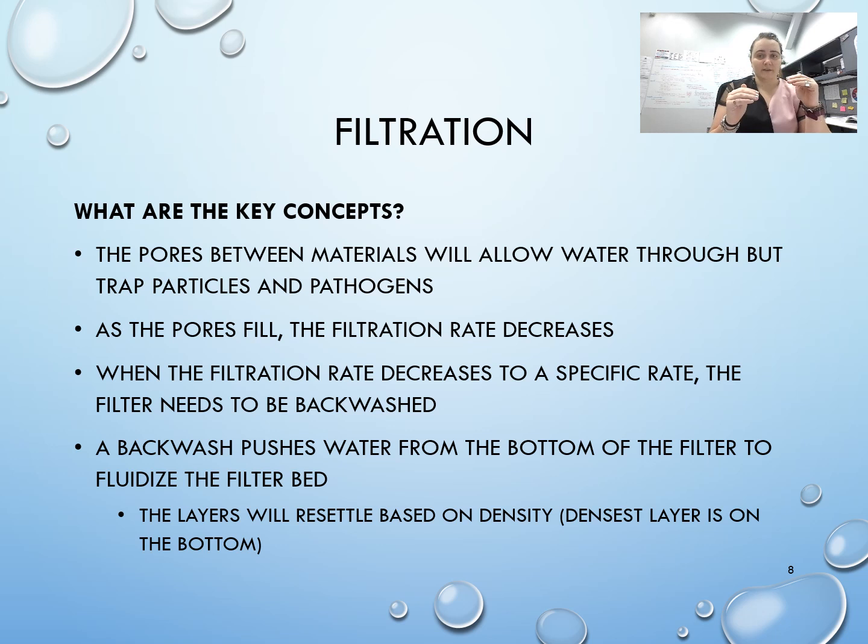As those pores fill, the filtration rate decreases. It's now harder to push water through because the pore spaces get smaller and smaller as they get filled up with these particles and pathogens. So when that filtration rate decreases to a specific rate, the filter needs to be backwashed. Normally we monitor the filtration rate and we monitor the turbidity coming out of the filter to know when to backwash.